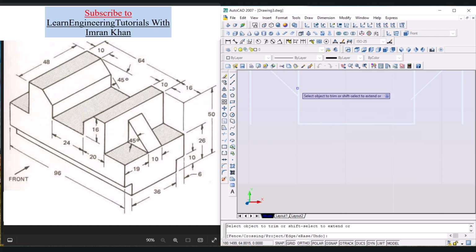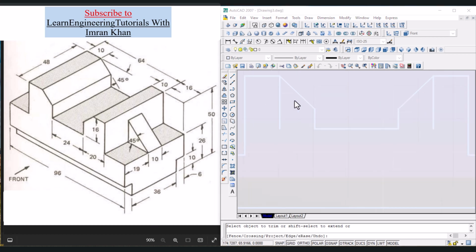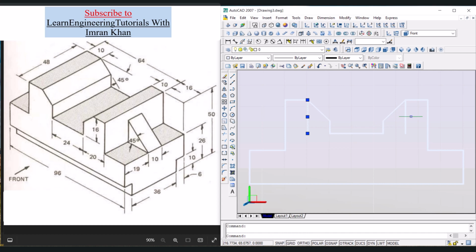Press escape. Now use trim command, so TR, enter, enter, zoom in, click and click, click and click. So now we can remove these extra objects. So press escape, click, click and press delete.